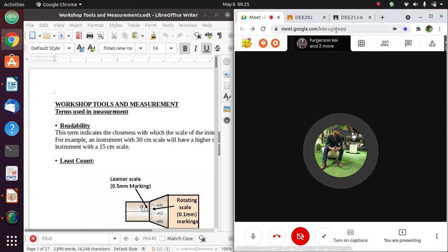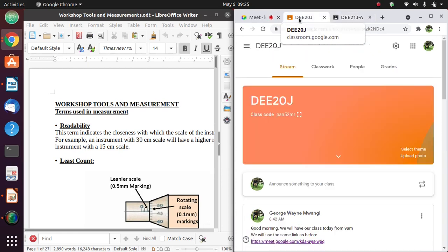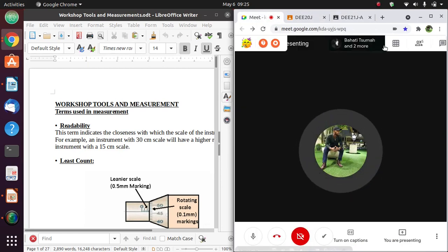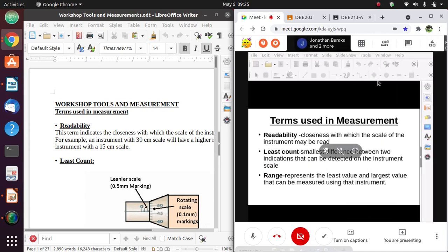So if I was to look at those individual divisions, from one division to the next of this 30 centimeter ruler is 0.1 of a centimeter, and that is the least count of this ruler, the least measurement that this ruler can measure. That is what we call least count. Different scales and different instruments will have different least counts. A vernier scale will not have the same least count as a micrometer, as a ruler. They will all differ depending on the type of scale you use.